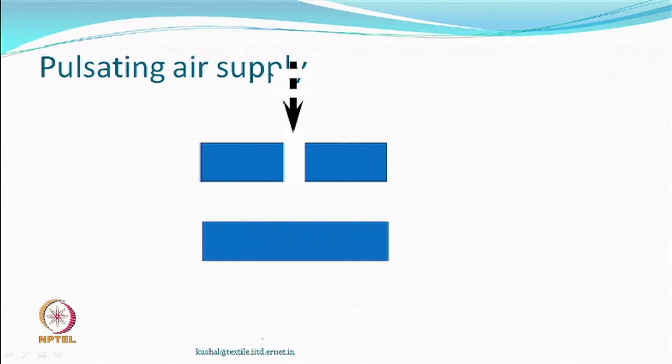So, directly it is not impinging on the yarn, it is actually coming in one way or the other and then trying to work. This whole process, people thought that you can actually have an actuator where the air is being impinged directly onto the yarn in this manner, but is pulsating. So, you have a control. When the air is there, there is an interlacement, there is no air, there is no interlacement. So, you see that so many people wanted to try so many types of designs, so that you get what you want to get.